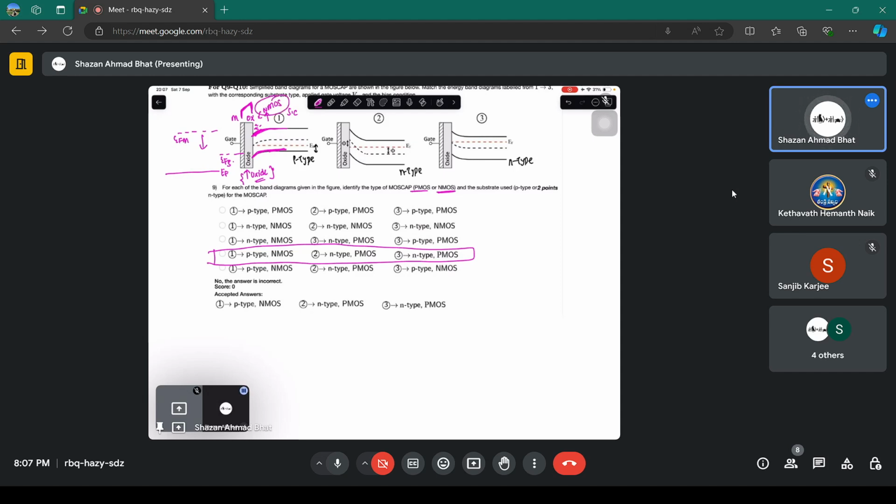N means electrons are the charge carriers, and current is going to flow because of that. When you make a MOSFET, in the MOS, when the carriers below the oxide are electrons, you call it NMOS, where N is the electrons. In the N type, when you have the holes here, you call it PMOS. P means because of holes, the carriers are the holes. Again, you have the N type here, you have the holes here. This is the accumulation region.